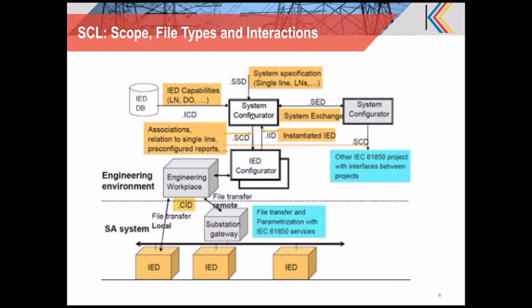The first thing we need to do is the system specification, that is, the substation. The SLD of the substation and its elements, like transformer and breaker, are all defined in this system specification, and it is configured as a System Specification Description, an SSD file.